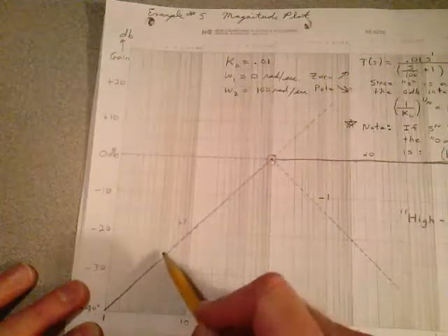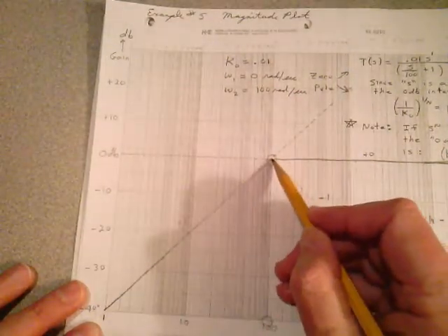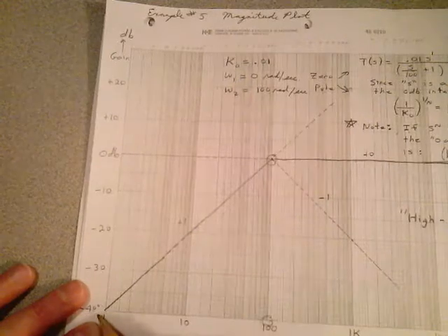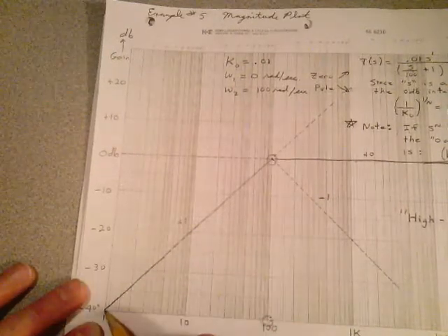This has to be coming in at plus 20 dB per decade. So I know that point, and I know this point. I draw a dashed line. So the first line you're going to draw is a dashed line from here the whole way up through here. You know, one dashed line. That's the influence of that single S term.